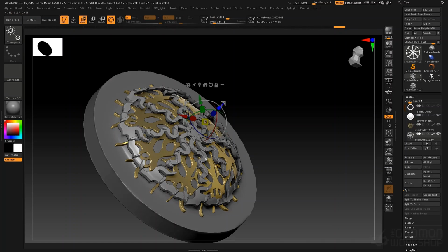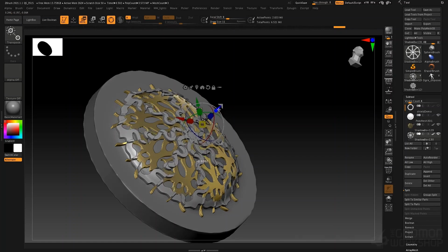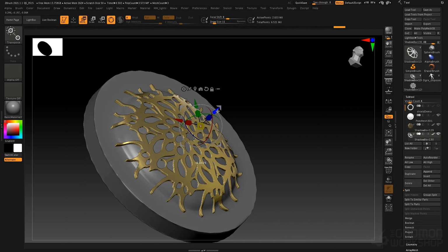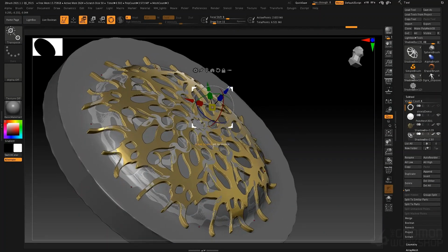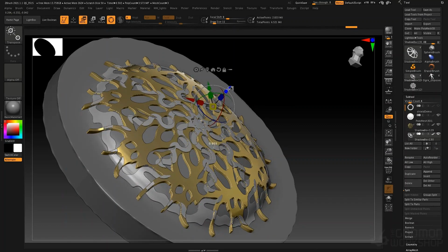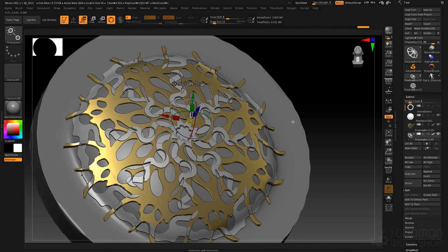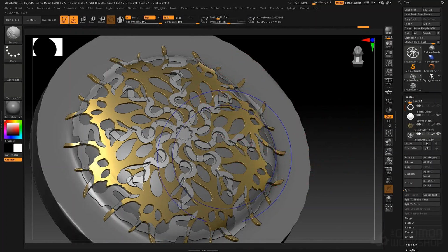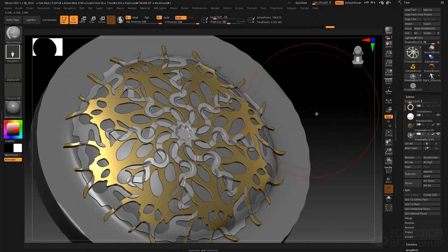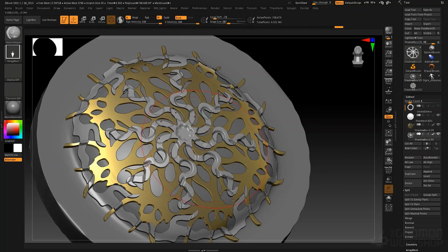I'll take my transpose gizmo, bring this down in the Z-axis, and then that will sit perfectly on that surface. Maybe I want to move this up just a tiny little bit, bring it up like that so it's sitting on top. And then we can further sculpt on this if we wanted to smooth this, say, to take down some of the jaggy edges. We could do that. I'll step down a subdivision level now. And then we can smooth that back so it's not quite so jagged. And we can further adjust its positioning, whatever we think is best.